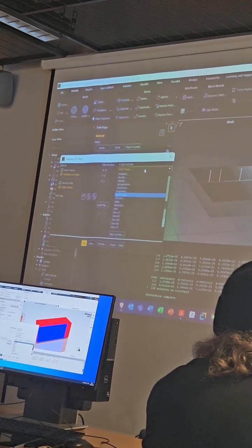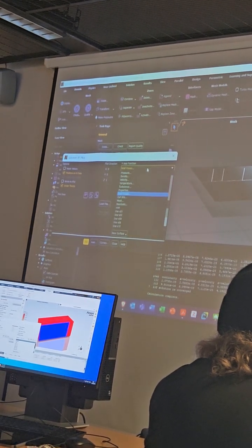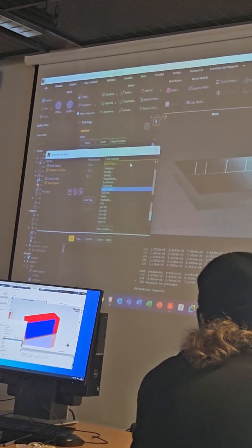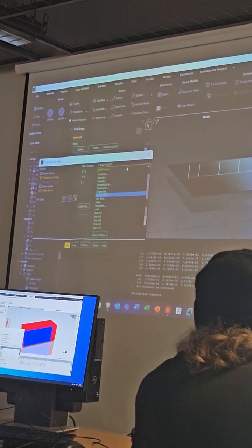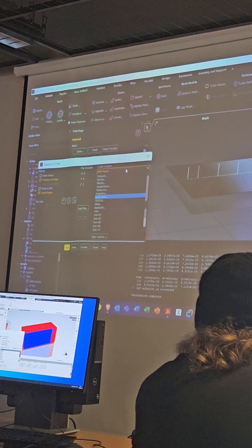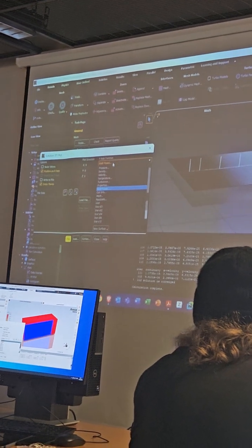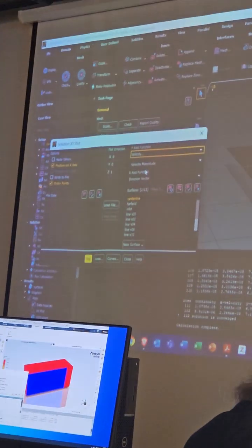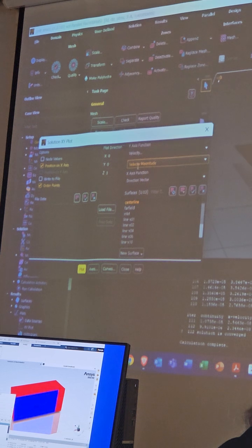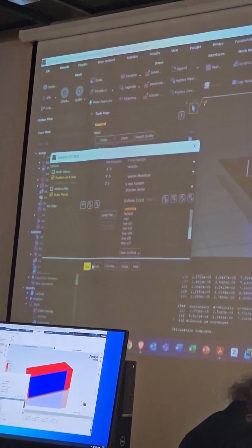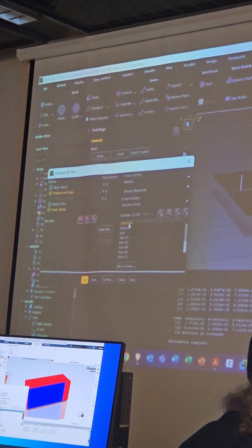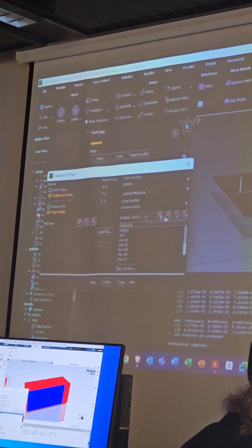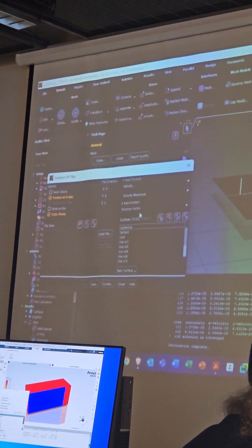In this case, we have basically constant density, 1.17. We have constant viscosity, so the only distribution that we need is the velocity. So in the y-axis function, we select Velocity, and we want to show the velocity magnitude. Then we select the right lines, not the center line, because there we have no-slip wall condition.